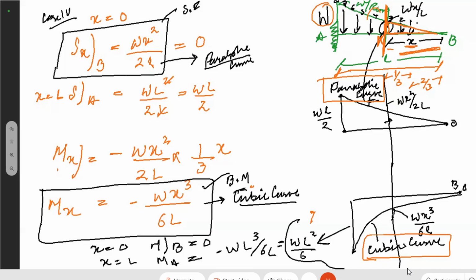Firstly, here you have to see what you have to draw. You have seen the bending moment at any point. What is the moment at x, or the shear force at x? It is actually the equation which gives you the bending moment at different points. Then you give the end condition that I want to know the bending moment at point x equal to 0. It could be when x is equal to 1, it could be when x is equal to 2, depending upon the spans of your beam.